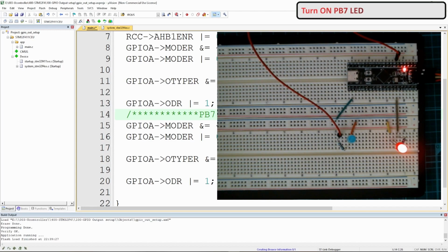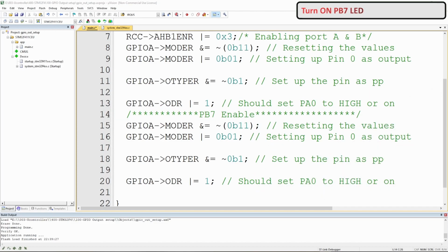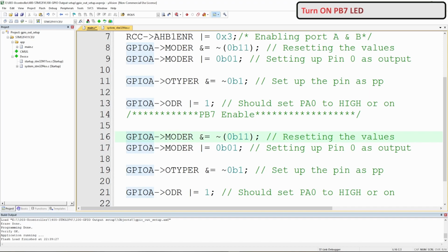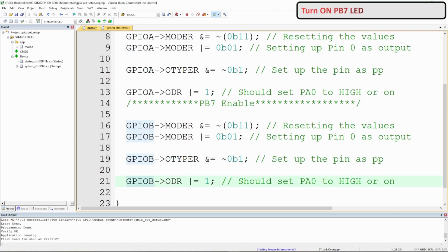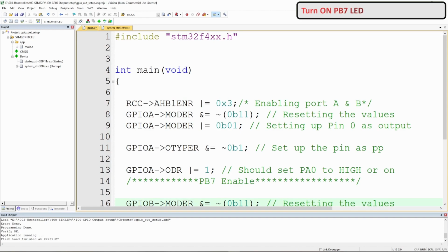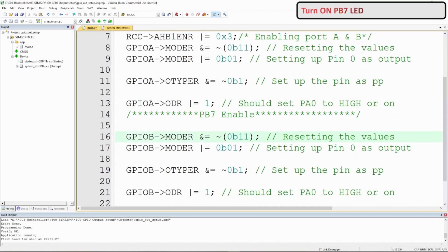Okay, so let me hide the camera now. So you can see the picture. I copied back all this GPIOA, and what I need to do first is change it to B because it's exactly the same thing. Ports A, B, C, until H, or up to the number the microcontroller has, do have the memory already allocated within this library. But here, I'm looking for pin 7.